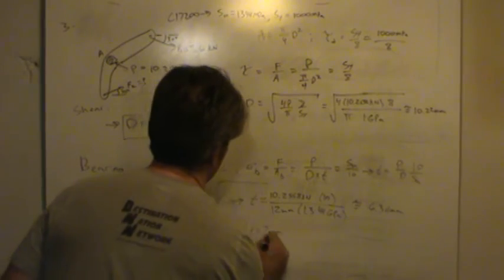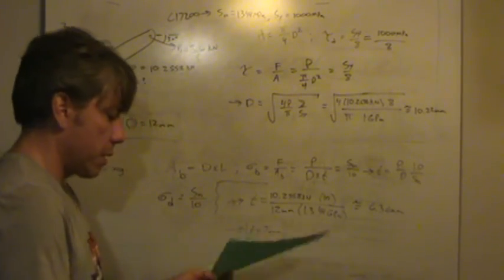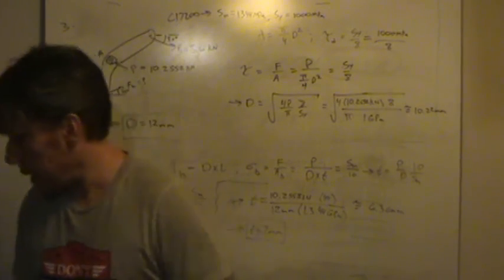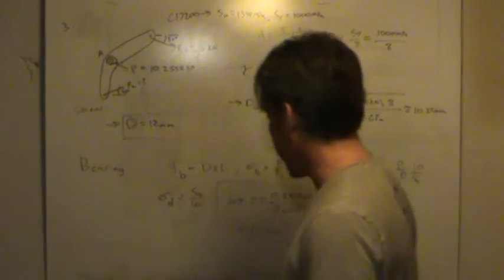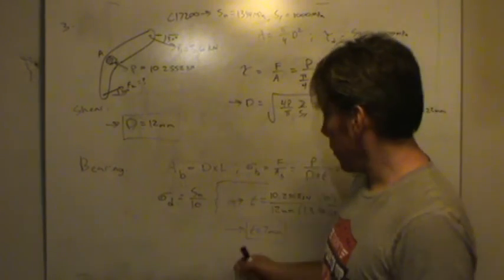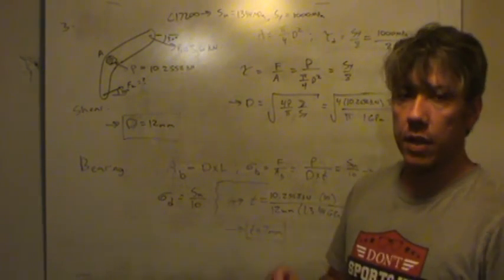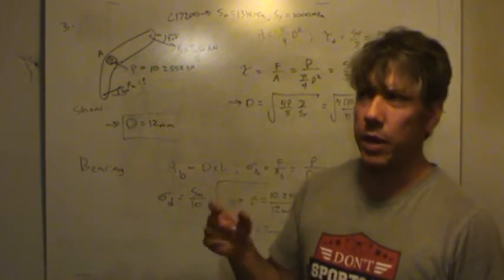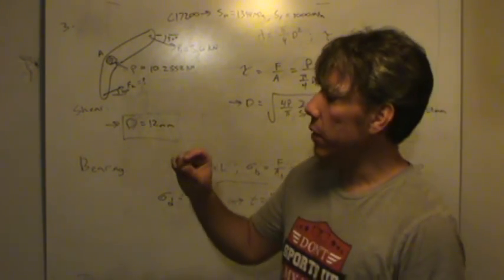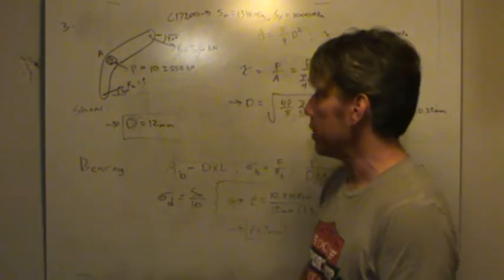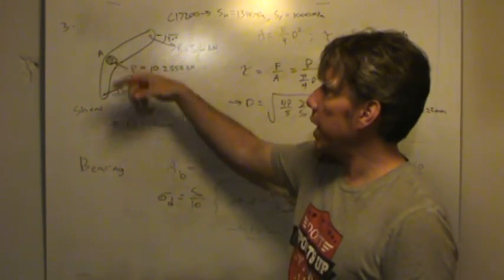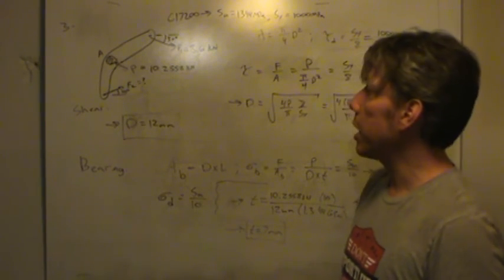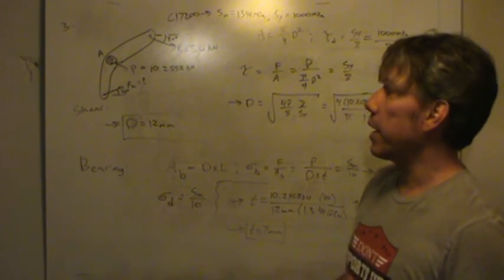Now that's not a first but a second preferred size. The reason I did that is because this probably would not actually be the specification. 7 millimeters is not all that thick. 7 millimeters, 8 millimeters is about 1/4 of an inch or so, if I remember right. Anyway, 7 millimeters is not terribly thick, so it's possible that this could be made out of sheet metal, which follows gauge sizes, or it could be made out of stock steel.